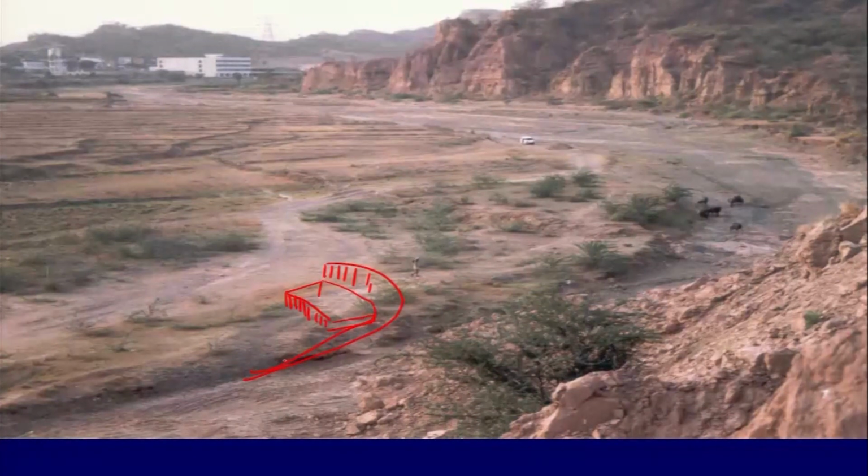And what is happening in the toe here is that this material is getting held up. Now this is the concept we are talking about, rotational slides. So we have multiple scars, and at places we will have extension cracks, and here we will have some compression, and these are our definite planes here.